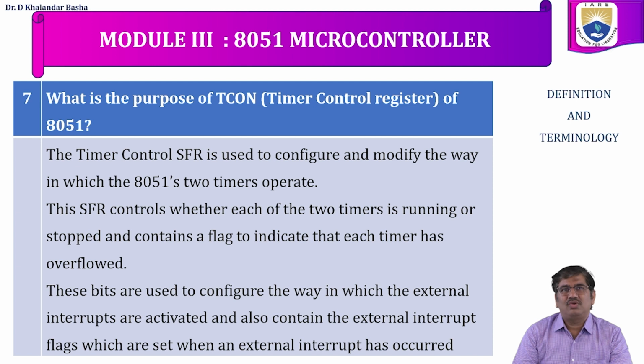This SFR controls whether each of the timers is running or stopped and contains a flag to indicate that each timer has overflowed. These bits are also used to configure the way in which the external interrupts are activated and contain the external interrupt flags which are set when an external interrupt has occurred.